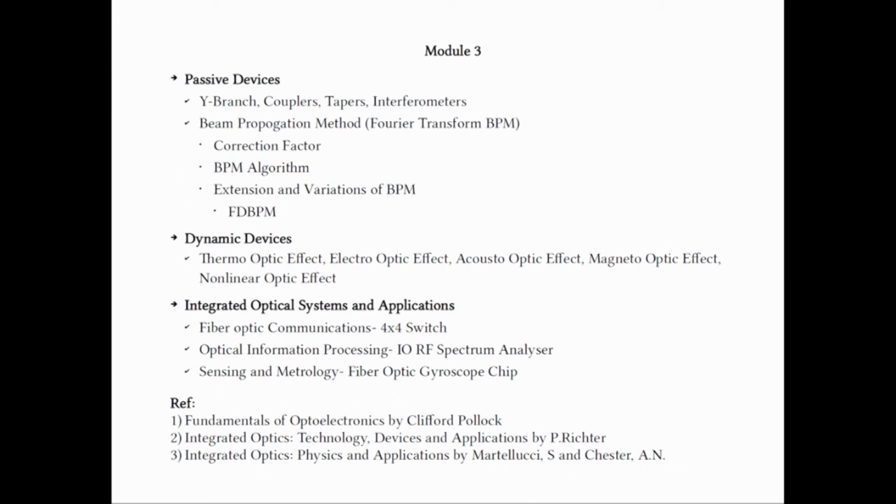So, the resulting output optical field could be considered as being the effect of all these superposed gratings, and we can calibrate the output field such that it corresponds to what truly represents the RF spectrum. Similarly, we can also reconfigure this as an optical spectrum analyzer, where we give the input signal to the light wave and the RF frequency is fixed, creating a fixed grating.